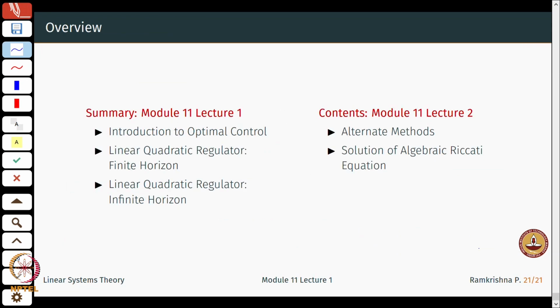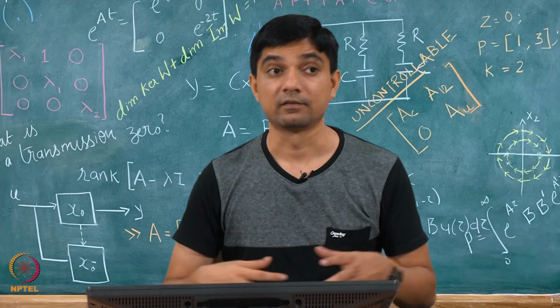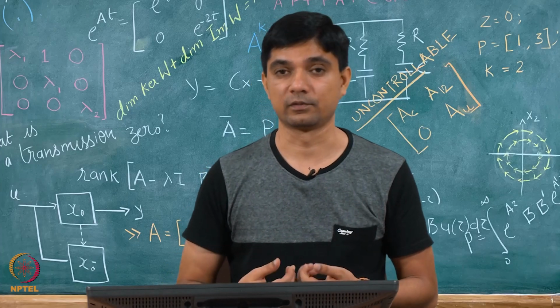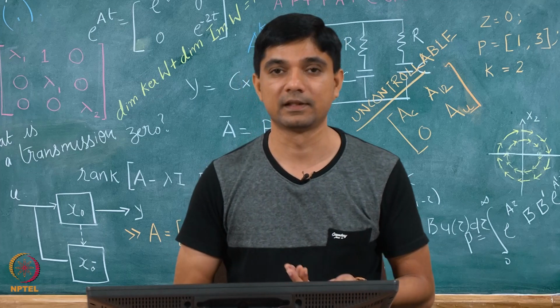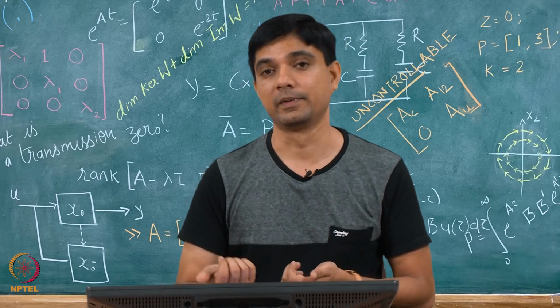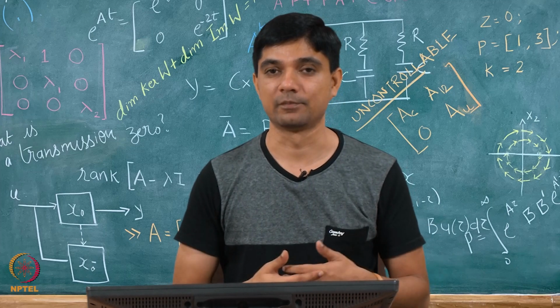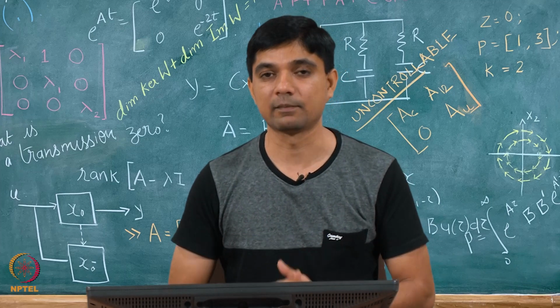In the next lecture, we will look at another method of solving the same optimal control problem, and I will give you a brief introduction to the solvability of these Riccati equations. Under what conditions do I get the solution? Are there simplified methods to check whether or not there really exists a solution? How much is controllability important? How much is stabilizability important, and so on? So that will come up in the next lecture.